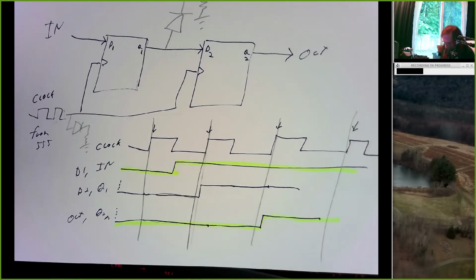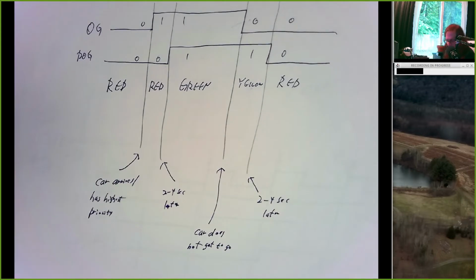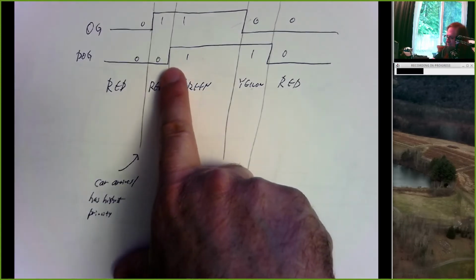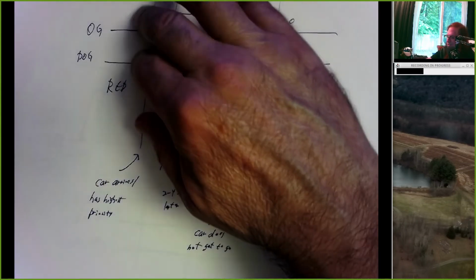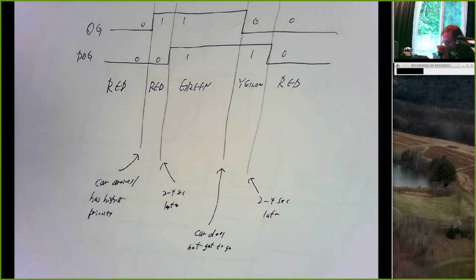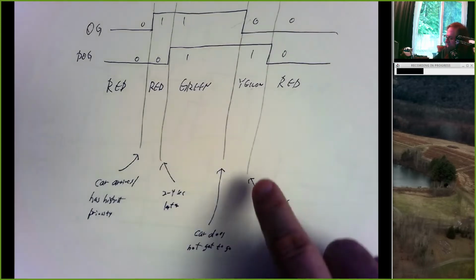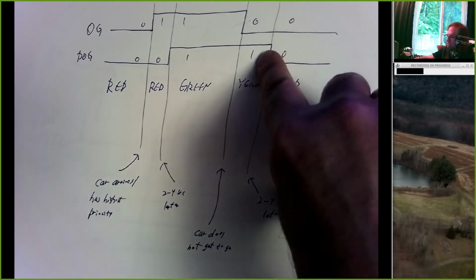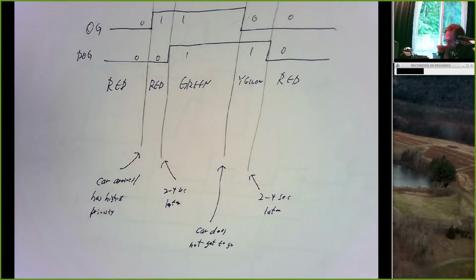And then experiment 2 is this business of taking the old permission signal, the old go signal, and the delayed version, 2 to 4 seconds, and looking at combinations of those can tell us what color our light should be. So we get a green light after we've got permission for a few seconds. We've got a yellow light if we just lost permission but it's been less than a few seconds. And we've got a red light any other time.